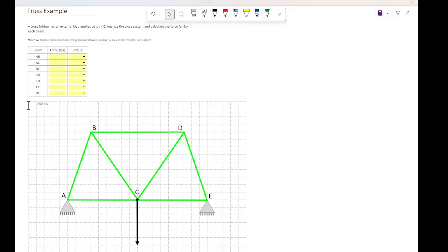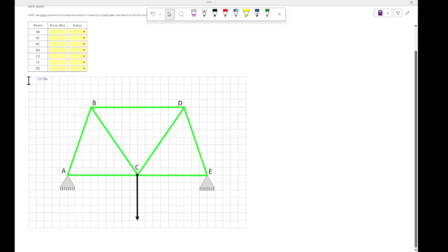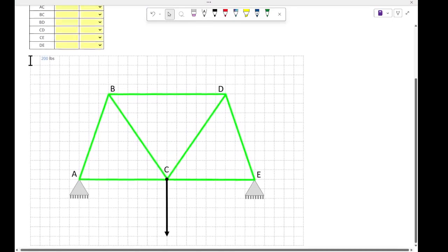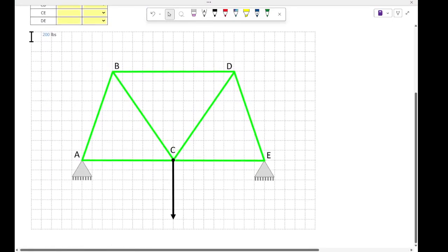in static equilibrium, meaning everything is balanced. All the forces everywhere have to cancel out to zero since, as Newton's second law would say, if we're not accelerating, there's no net force. So what we end up having is a puzzle here where we start to break down what is happening at each point. So what we're going to do is look at each part of this truss, and we're going to break down each joint and identify what's happening at each spot.